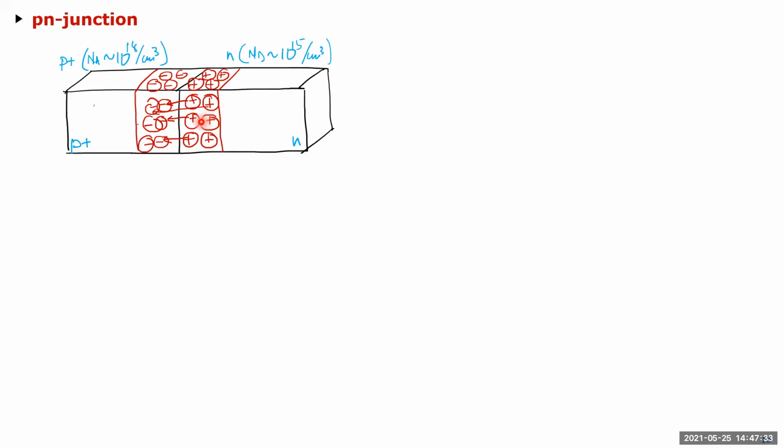This is what's called depletion charge. It's called depletion because the atoms are depleted of their carrier, which is the electron here, so the majority carrier is electron. And these charges are immobile. You can't conduct current through this. It's just that the overall charge in this unit volume is positive. As the electrons move, they're building up this electric field, and the force against the electrons is increasing. At one point, the force in this direction and the potential difference existing between the electron and this equate, and then it stops. And that's what's called the built-in potential.